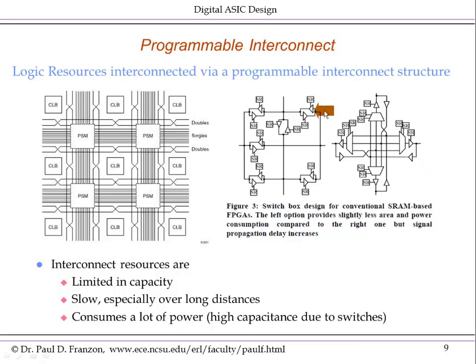The way on the left, I have tri-state gates controlled by registers. The idea is most of them are in the high impedance mode. A few of them are set to transfer the input to the output. Those that are set to transfer the input to the output determine the direction and the connectivity of which of these pins is the input, which of these pins is the output, and their connection. Notice this is a 1-bit, 1 input, 1 output block.